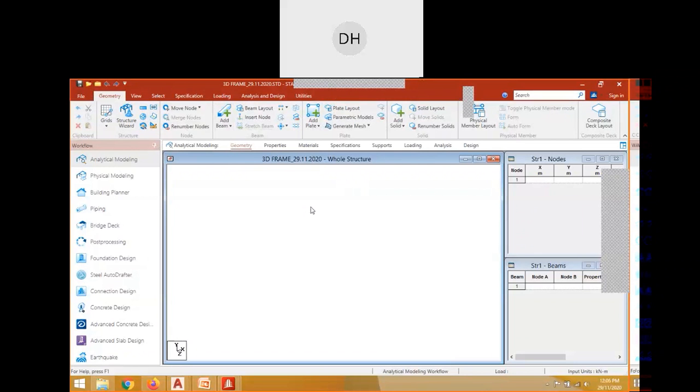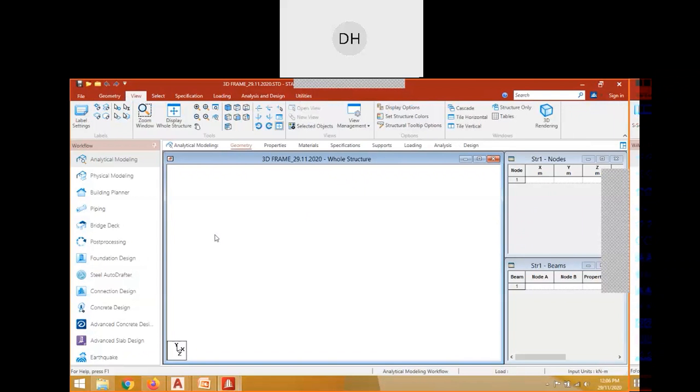But if you have, say, a water tank, then you can go with plate type modeling, where you need to model all the plates, meaning the walls of the water tank, the cover slab, everything. There you can use this plate type command. Then there is also the add solid command. These are the basic commands in the Geometry tab.